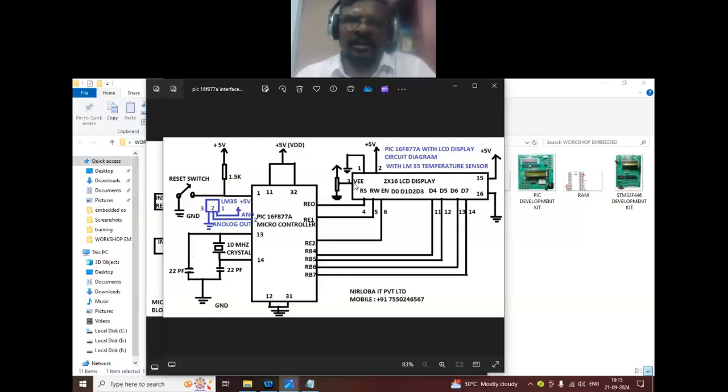In this LCD the message will be displayed. Say you want to display hello world, it displays in black color, but it is not exact black, it's called gray color. The darkness, the intensity of the characters, is based on this contrast voltage, VEE.